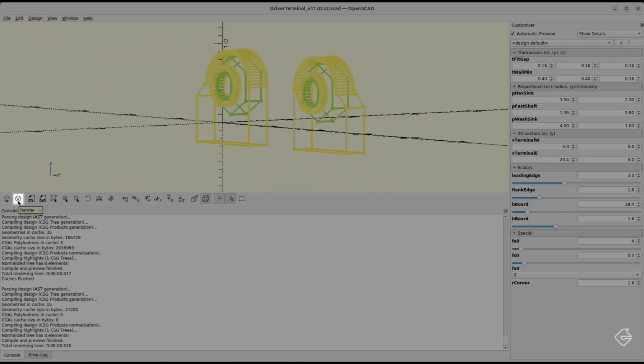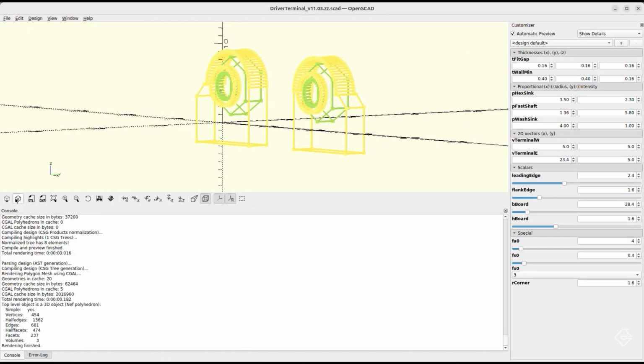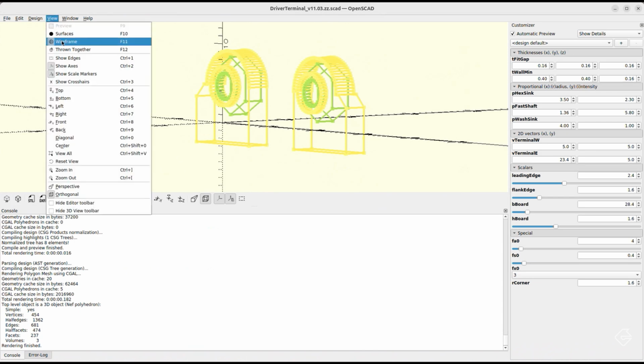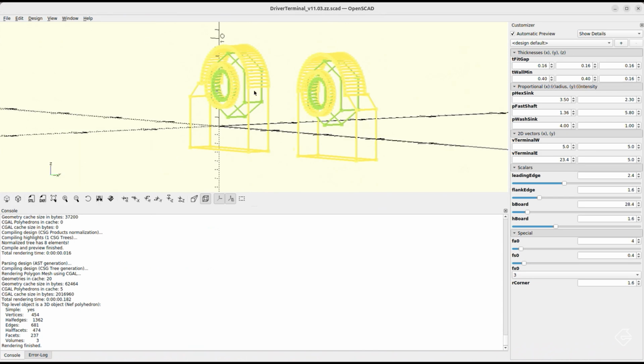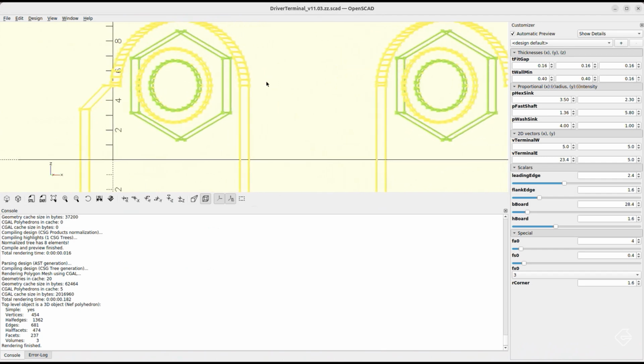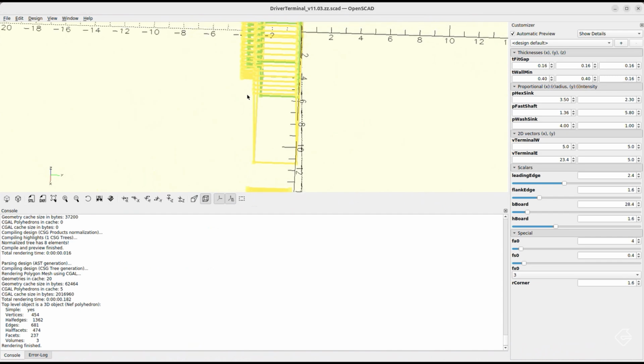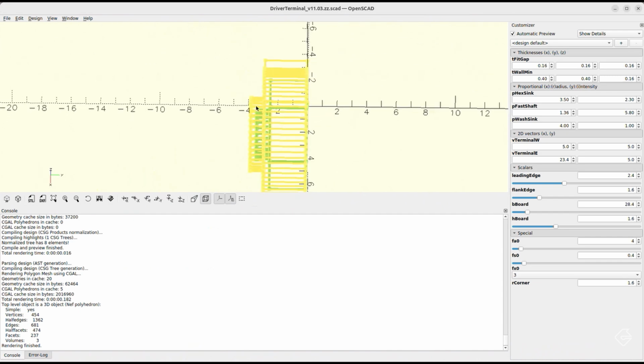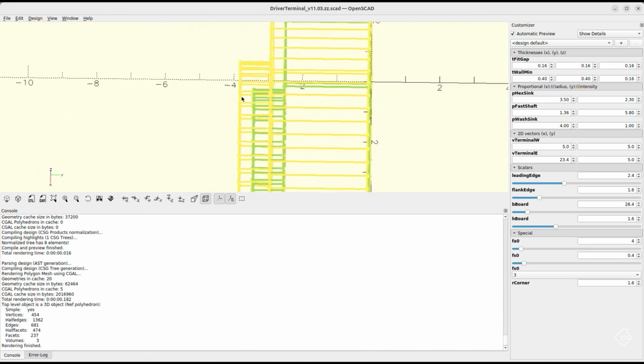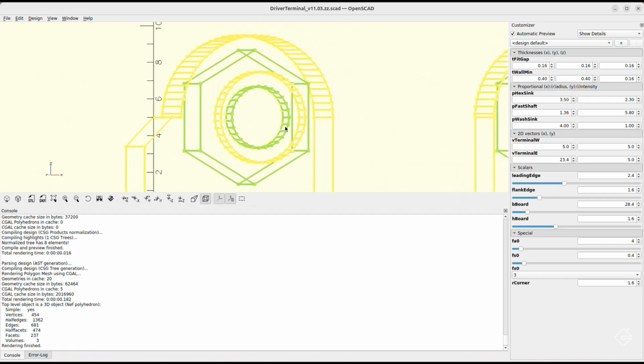And I don't mean preview, I mean render. And that's this button over here. So just hit that render button, and you may need to highlight the wireframe once again to see this. But now with this wireframe selected, you can actually see where those vertices line up. And if we position this model the right way, you'll see how the hole ends up just a little bit behind the extension, which means it's being covered by material, and the radius of the extension sufficiently covers the radius